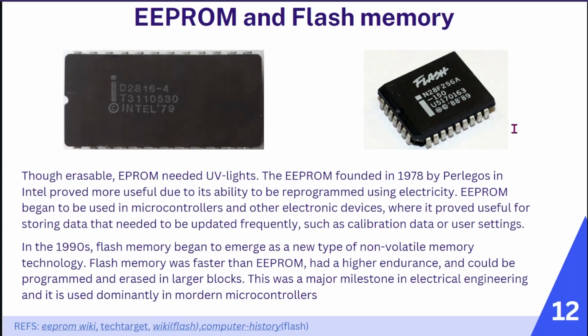Flash memory was first invented in the mid-1980s by Dr. Fujio Masuoka at the Toshiba Corporation. The technology represented a significant improvement over existing memory technologies, particularly the EEPROM, as it allowed for larger memory capacity and faster access time. EEPROM memory uses a series of transistors to store data, with each transistor representing a single bit of data. In order to rewrite this,